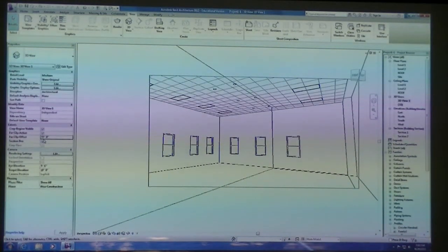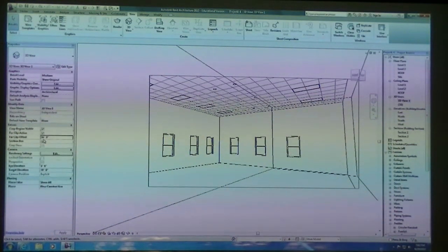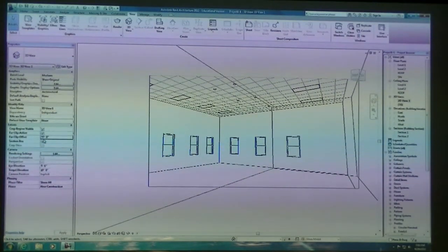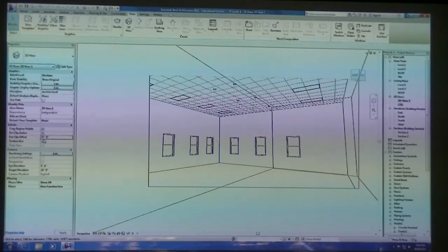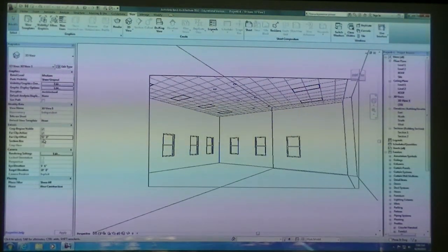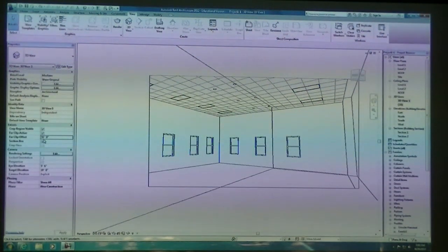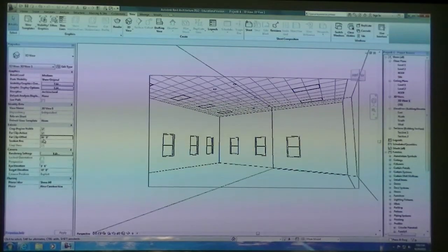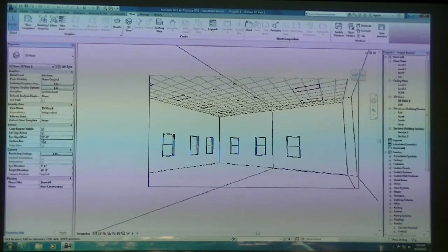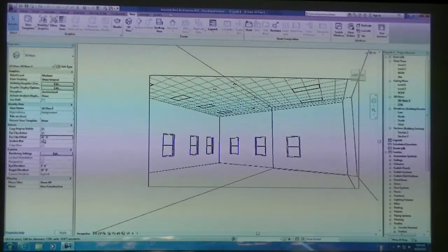Especially if you have something in the view that's far off in the distance, like your city block that's installed within our hotel model. You don't want the buildings all the way at the other end of Manhattan being rendered at the same time. So use that far clip offset, and that will really help speed up your render times as you get involved with interior renderings.